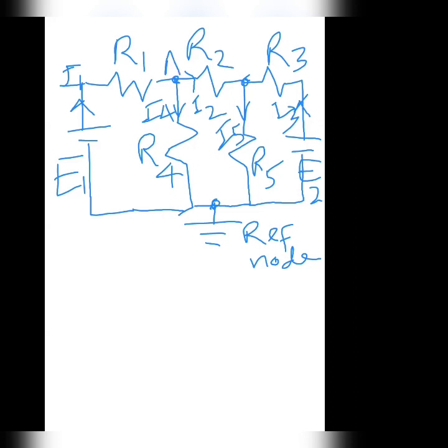Say this is A and B. So the voltage which is corresponding to this nodes can be assigned as VA and VB. So this is the potential which these nodes are having. Now we can apply the KCL and potential difference. So first add that this I1 is incoming current, this I2 and I4 are outgoing current. Okay, so the first equation will be I1 equal to I2 plus I4.